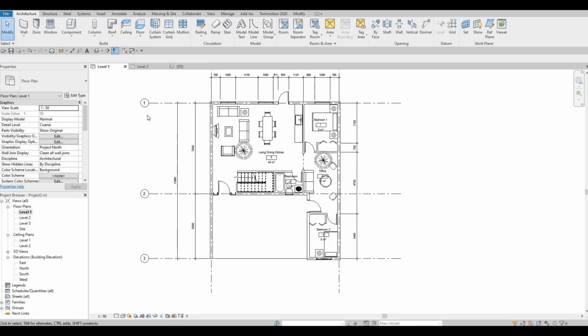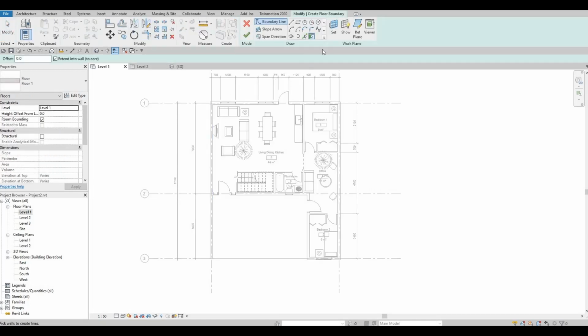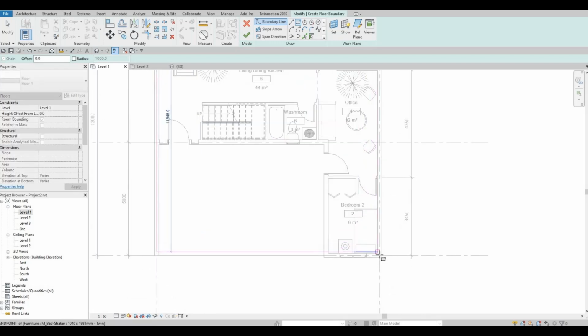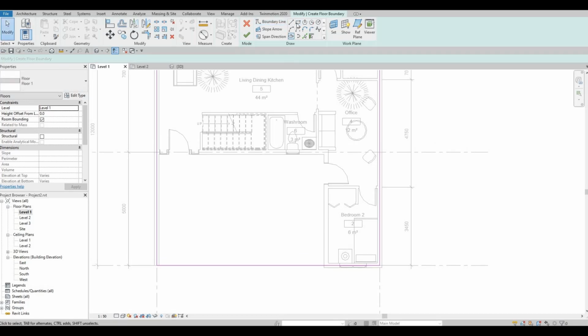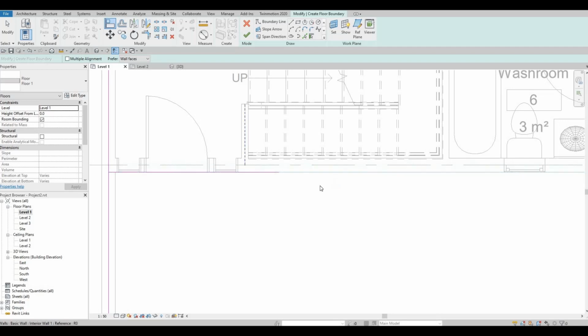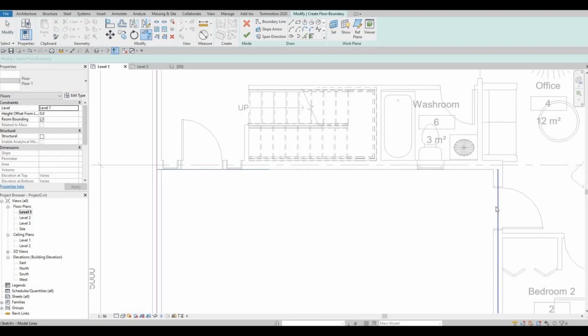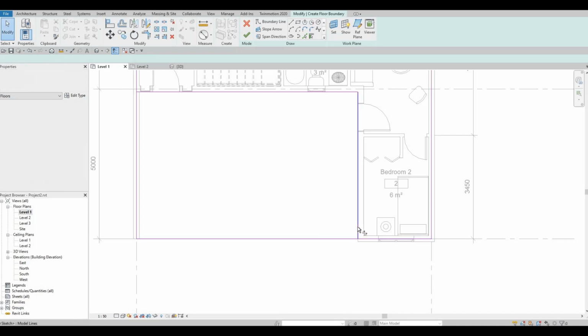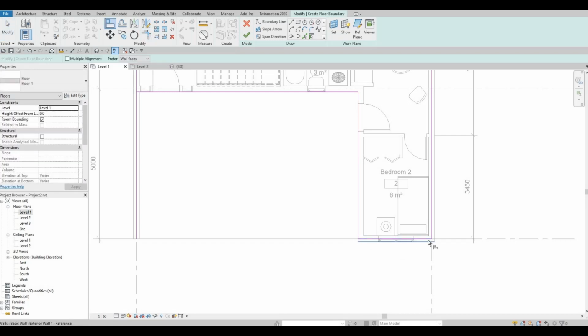Go back to level 1 and let's add the same floor on this area. So I always start with rectangle so it's easy. And then after that, I create something like this and then trim and extend afterwards. I'm going to align this for now and then TR, AL on this. I realized that this is the one below, so we don't need to put it in the middle.